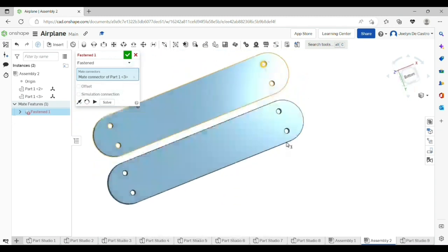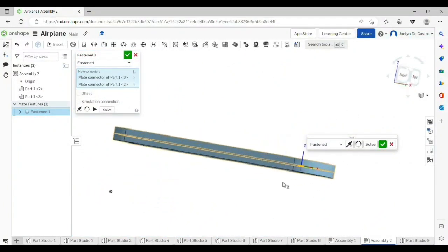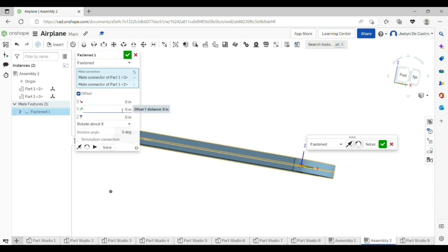But they're actually separated here. For the separation, create an offset. The offset is going to be a Z offset and it will be from those two faces. The value will be 2.25 and that will create the space in between. Accept this.